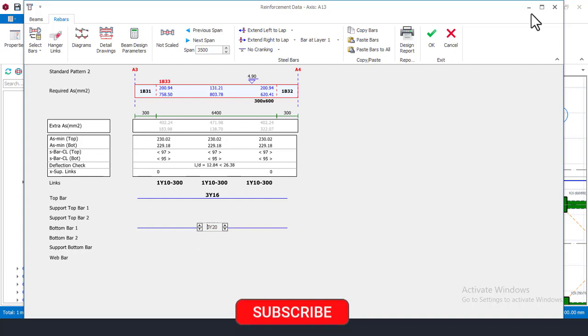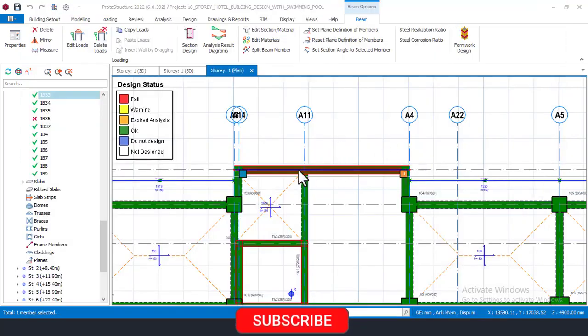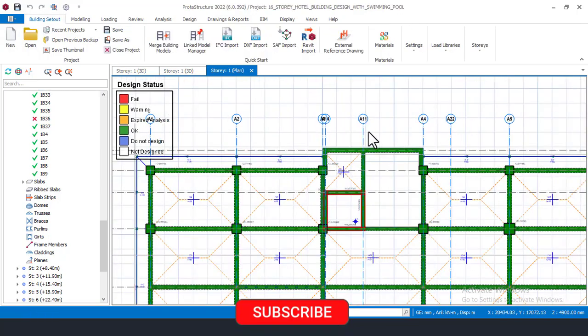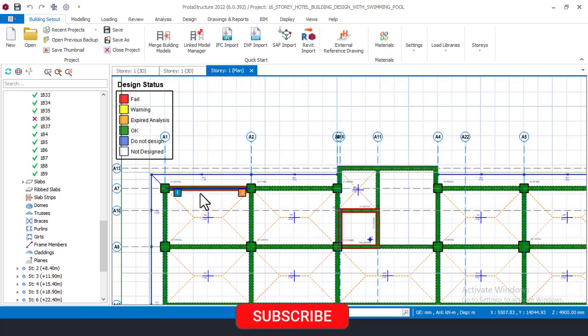And decrease to Y20, so to 3Y20 as it is. So with this right now, I have to check this beam, and this beam looks what? Okay. So right now come here and click on what? Okay here. So with this now, I have now checked this particular beam here, and I am okay with that, the beam is okay. So always check your beams, alright, to see the kind of reinforcement that the software is giving you. So I'll come again right now and check on this.